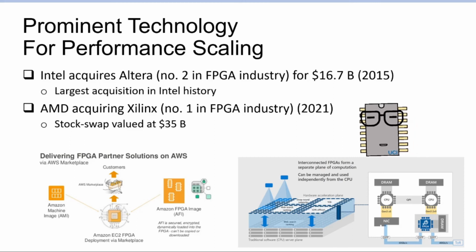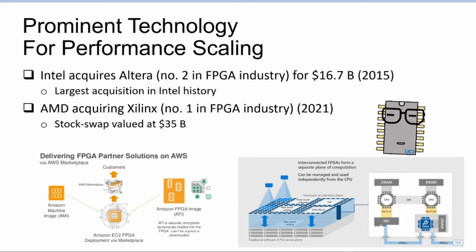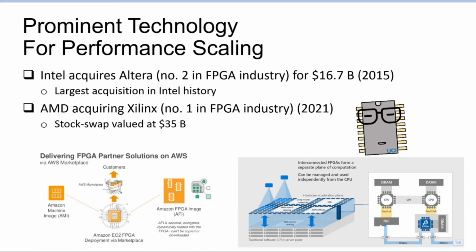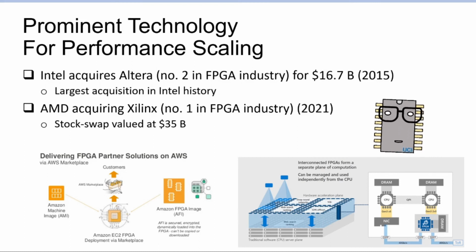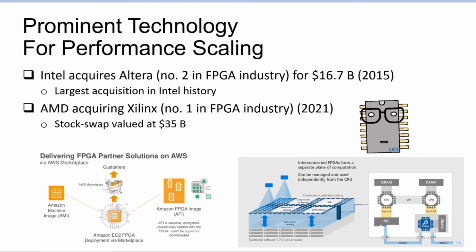As opposed to if Microsoft wants to do something similar, and they trained the model and discovered, oh, this model works better with a specifically structured 8-bit floating point format, then instead of leaving some resources idle, the so-called Microsoft Brainwave platform can be reconfigured on the fly to use the available FPGA silicon resources to spawn that specific number of specific 8-bit floating point operators, which Microsoft claims is an efficient trade-off in performance.